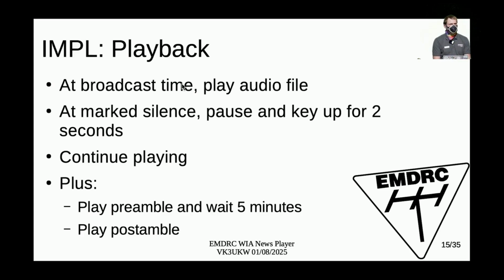Then you just want to play that back. So at the broadcast time, you play that audio file, and whenever you come to one of those silence times, you just pause, release the PTT, and like I said before, we have to do that for 2 seconds to make sure that the repeater actually resets, and then we just continue playing.